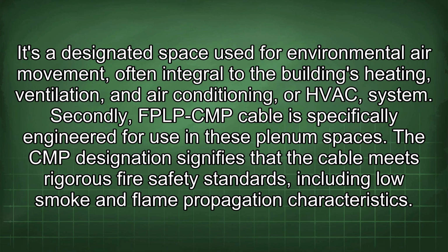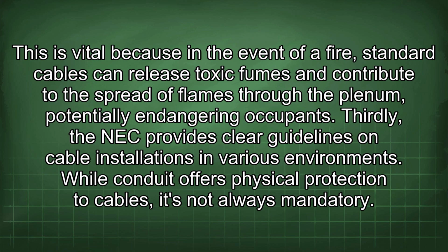The CMP designation signifies that the cable meets rigorous fire safety standards, including low smoke and flame propagation characteristics. This is vital because in the event of a fire, standard cables can release toxic fumes and contribute to the spread of flames through the plenum, potentially endangering occupants.